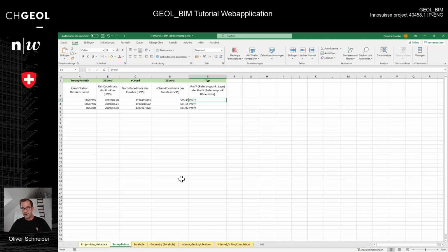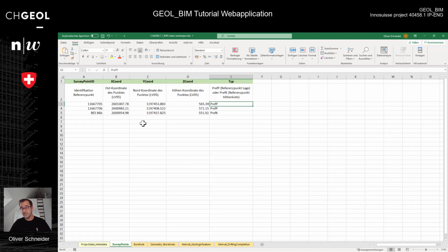Here we implemented a reference paper or reference study from the use case of buildingSMART Switzerland. We add directly in the IFC the survey point or the local coordinates, with pyramids for the placement, and for the height information we invert the pyramids to the top, and then have a geometry element and also the entity written out saying what kind of information it is. So it's quite an easy possibility to check if all my data is in the coordinate system using the same reference system.